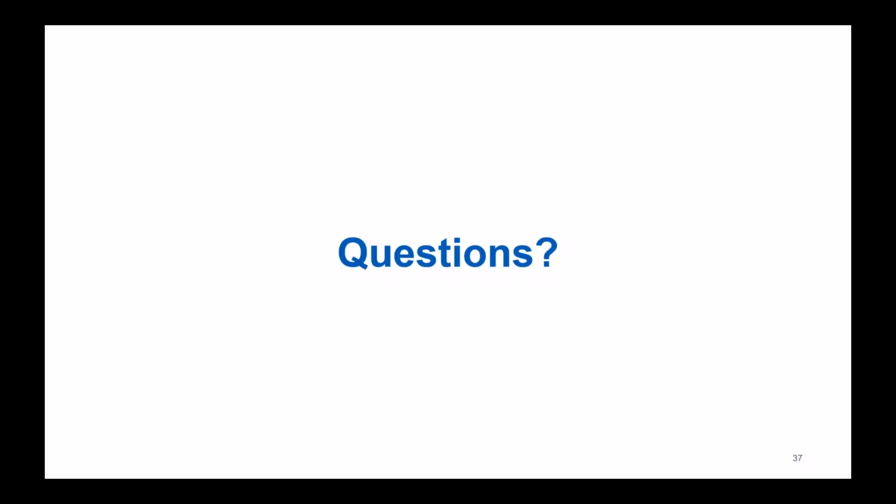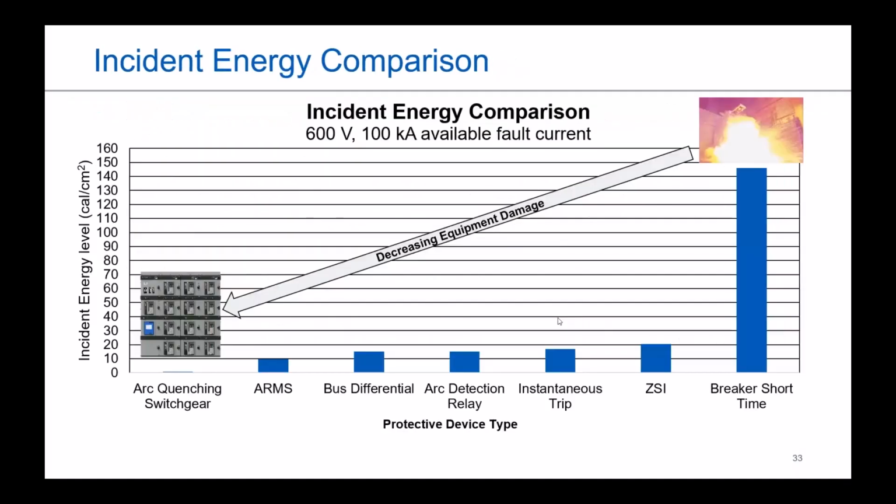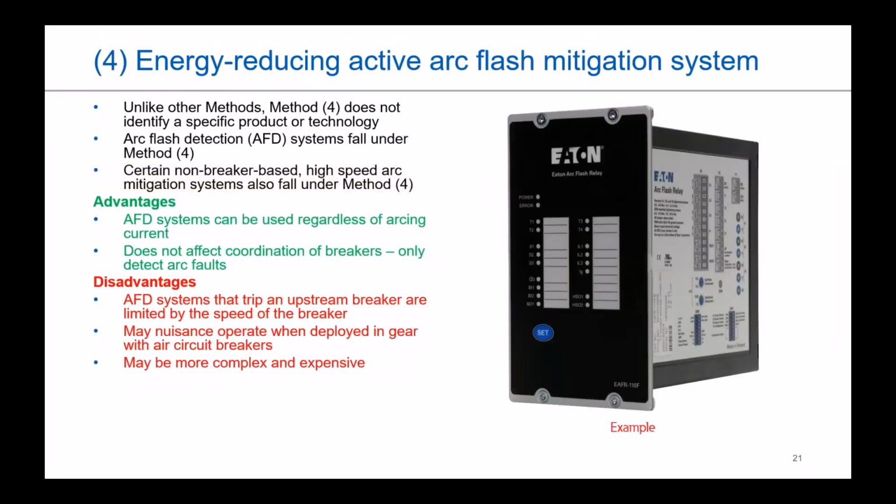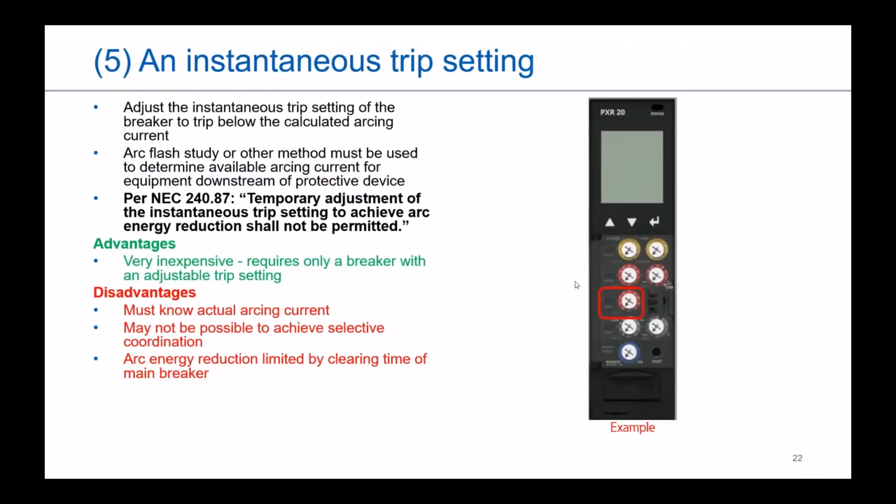Yeah, AJ, William had a question regarding the blue light on a maintenance mode unit. Is that required? There is, and again, I can't remember if the blue light is specific to a standard. I know that's our internal standard. I know there is a requirement to have an indication that the maintenance mode is active. What I have shown here is what's displayed on the gear. Typically, you will also have an indication that is local on your power circuit breaker as well.